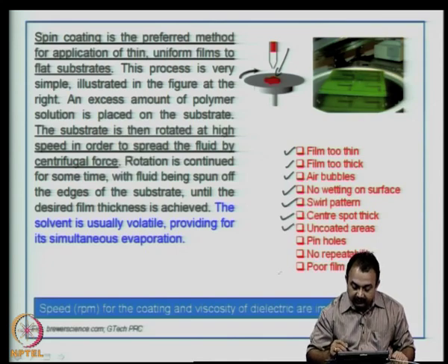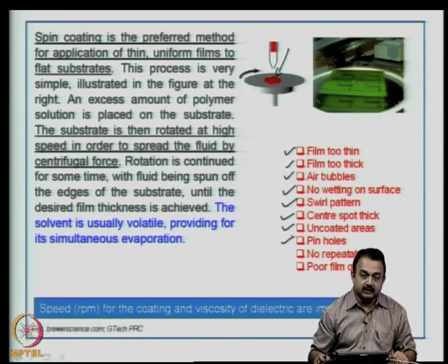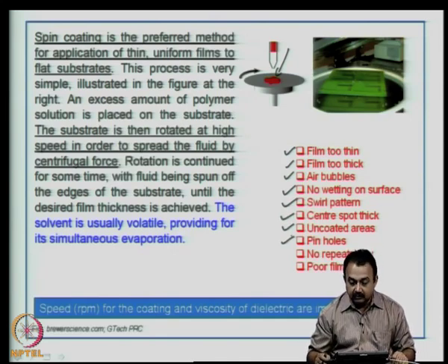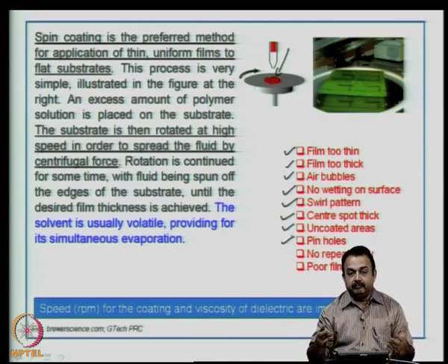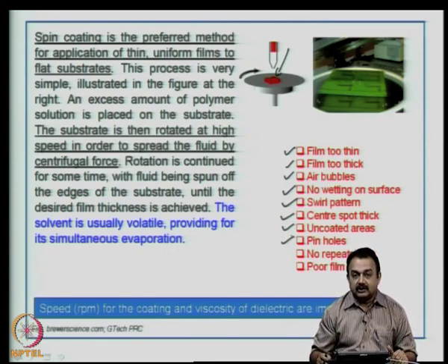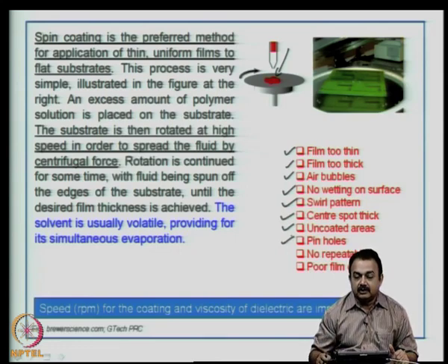There should be no uncoated areas. Pinholes are a problem because of external contamination when you are preparing the dielectric material, which will result in spots on the board. So, you have to work in a clean room, work in an area where there is dust control, where there is laminated airflow, and the material has to be mixed in an environment where the mixer, the equipments that are used and the vessels that are used to use this particular material have to be fairly clean enough.